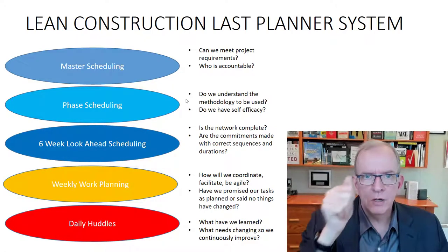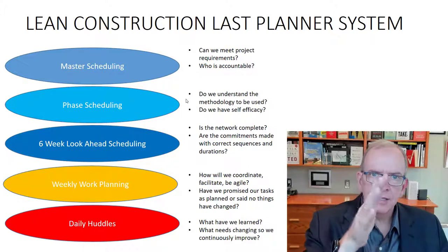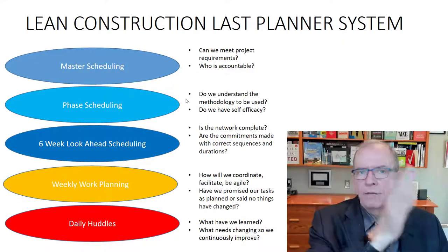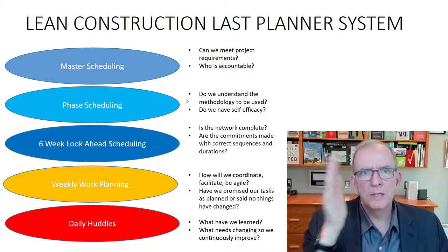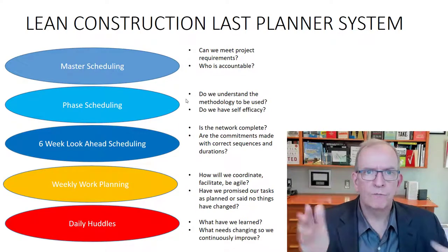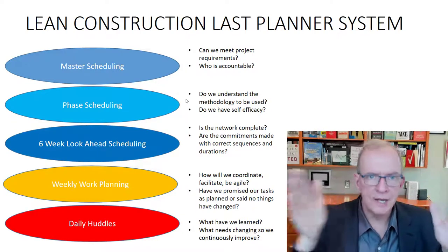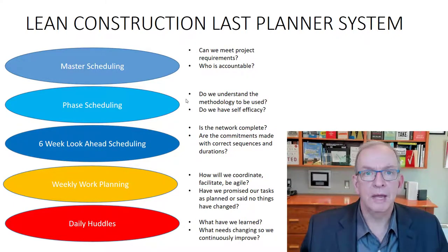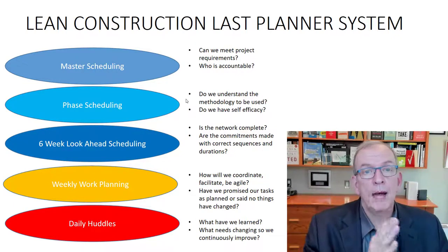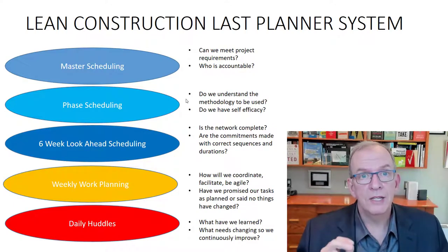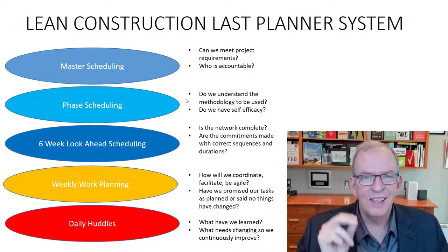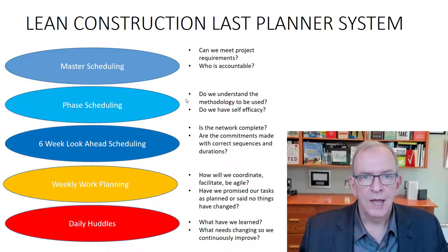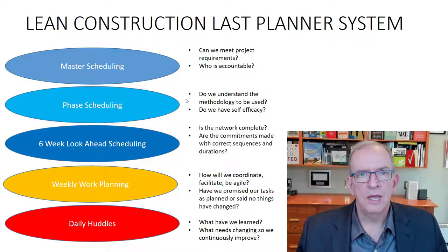And with the post-it notes, we're putting in the connections, the sequencing under time frames from 4 months out till today. I'm using 4 months, but really from the milestone date, next major milestone date, backwards to today. And we start at the end and we work our way backwards. That's a pull planning session. There's a lot of other information that goes into that, but that in its essence is what it is. And they plan that out during that pull planning session in detail.